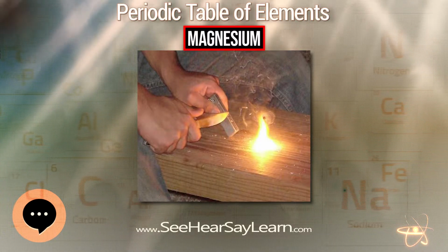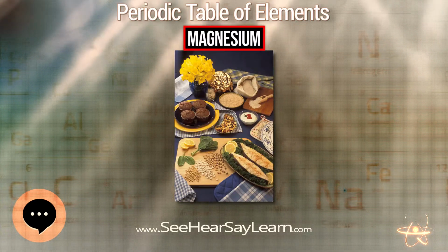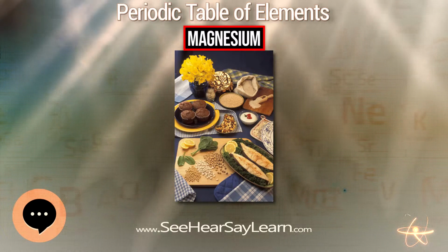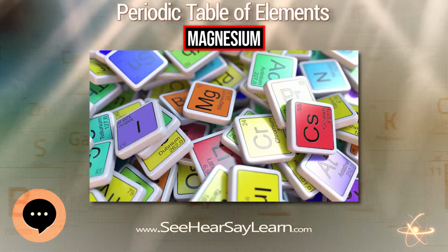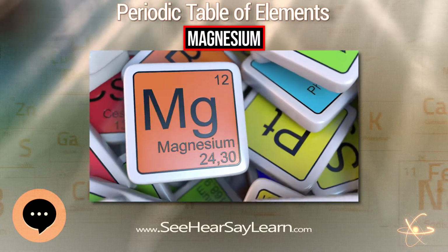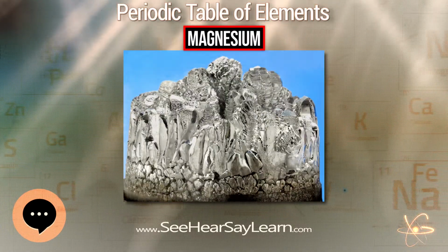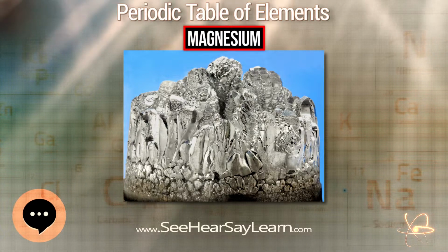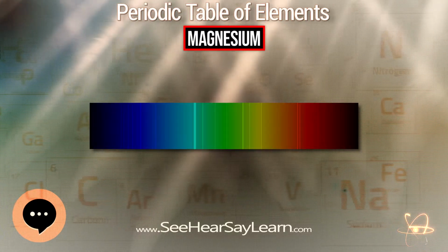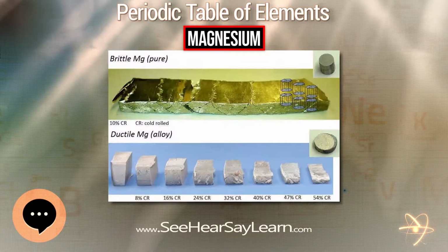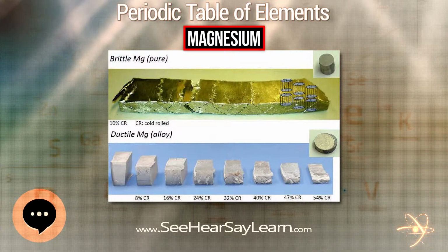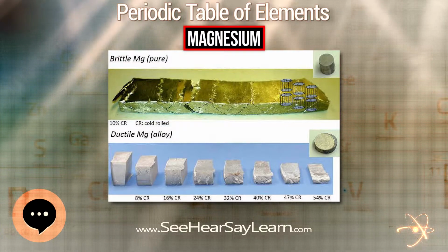Magnesium is highly flammable, especially when powdered or shaved into thin strips, though it is difficult to ignite in mass or bulk. Flame temperatures of magnesium and magnesium alloys can reach 3100 degrees C, although flame height above the burning metal is usually less than 300 mm. Once ignited, such fires are difficult to extinguish, because combustion continues in nitrogen, carbon dioxide, and water.